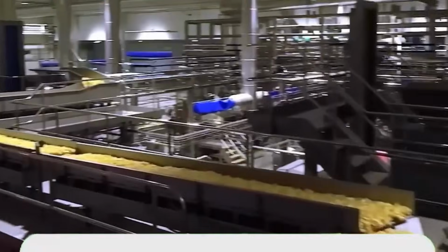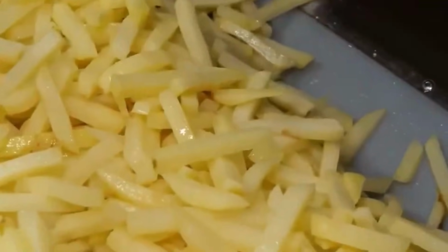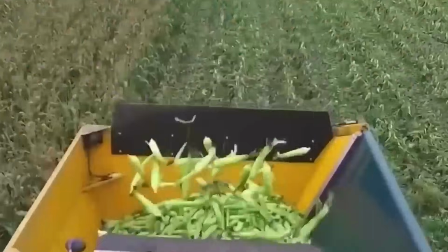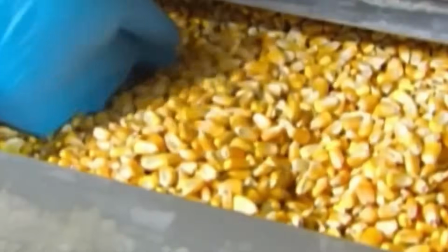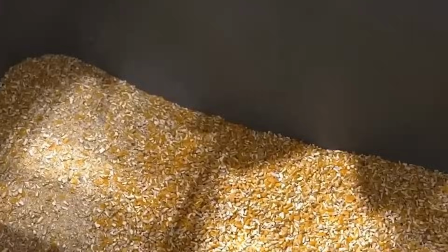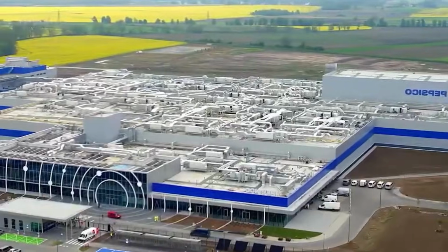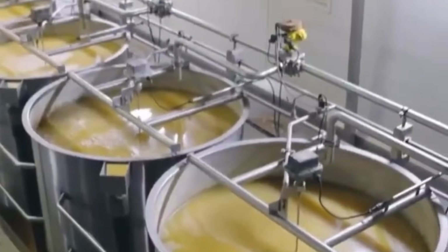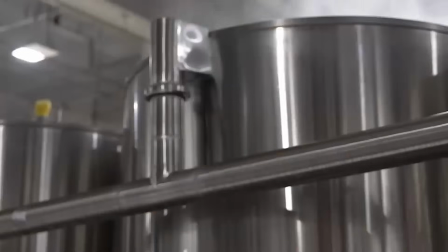Masa is fed into a sheeter system consisting of dual rollers, calibrated to produce a uniform sheet of dough at a thickness between 1.2 and 1.5 millimeters. The sheet is continuously monitored using laser micrometers that provide real-time feedback to the roller gap actuators. The dough sheet moves onto a die-cutting system where rotary cutters stamp out the triangle shape of each Dorito. Scrap masa is collected and returned to the auger to be reblended into fresh dough within a defined recycle ratio.